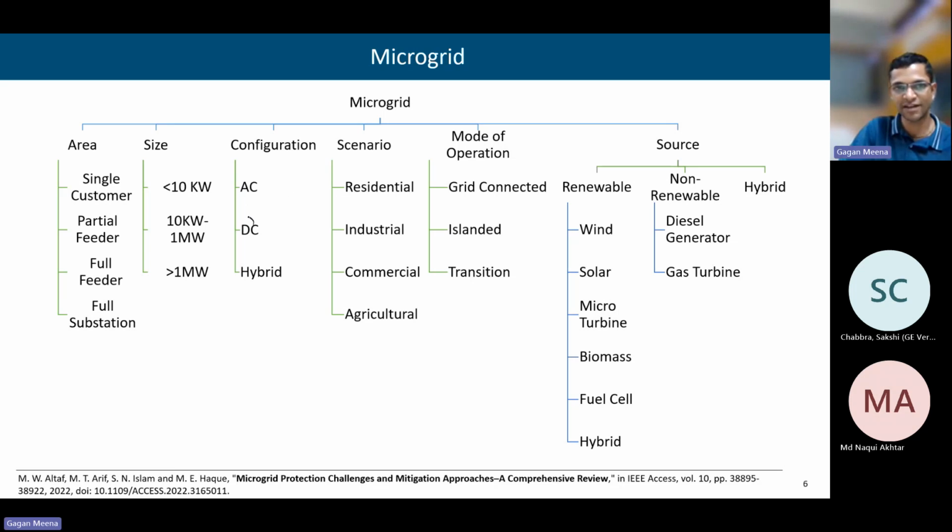But if the DC grid, a DC microgrid, is there, then that conversion stage is not required. Directly we can charge the battery. One conversion stage might be required, a DC to DC chopper or some buck converter, so the DC microgrid voltage level would be more than that which is required by the charger, that mobile charger. So one is AC, one is DC.